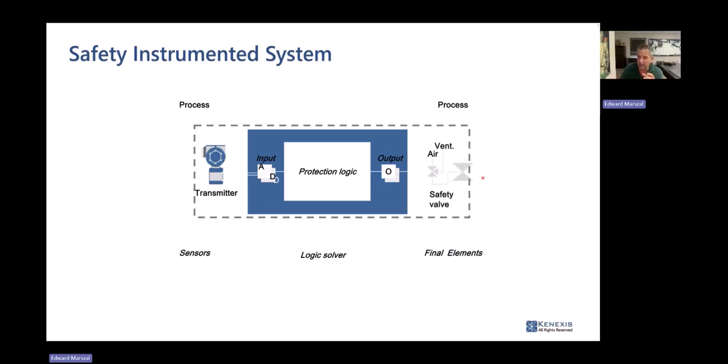So when I'm defining my safety function and I'm doing my SIL verification calculations, I need to know everything about the function from pipe to pipe. That includes not just the transmitters, but interface devices between the transmitters and the I/O cards, process connections that may impact your ability to achieve the SIL, input cards, output cards, CPUs, processors, other associated electronics and logic solver system, interface devices between the output card and the actual final element itself, like solenoid valves.